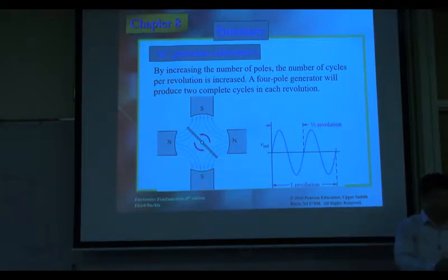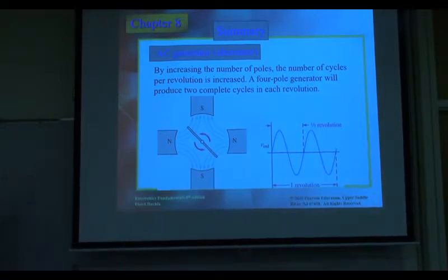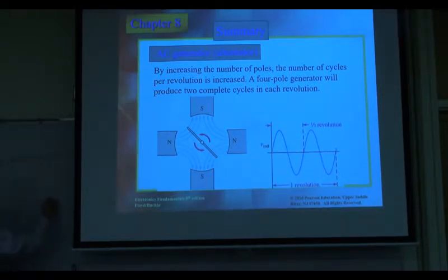Okay, suppose, everybody think about it. If the frequency equals 60 hertz, and I use 6 poles or 3 pairs, how fast should I turn this? 6 poles means 3 pairs, and the frequency equals 60 hertz. I want to know how many revolutions per second. 20 per second. Is 20 good? Yes or no? So 20 times 3 equals 60 hertz.